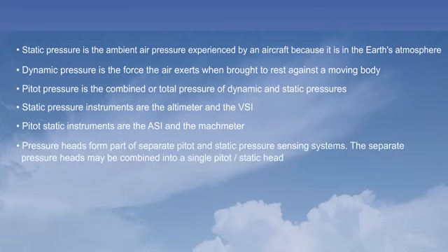Pressure heads form part of separate pitot and static pressure sensing systems. The separate pressure heads may be combined into a single pitot static head. A heating element will be incorporated into a pressure head to prevent the formation of ice.